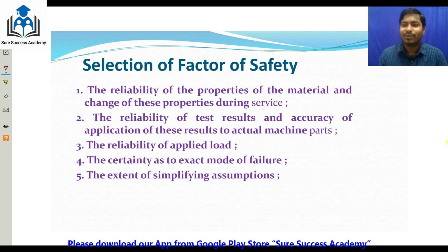Otherwise the working stress would be the same as the maximum stress, but in usual practice the strength of materials you calculate is not the same. This depends upon different fabrication processes, and also on the types of load we apply. Always we say static load, and really it is a static load, but there may be times when you suddenly increase the load. It is not always applied slowly.